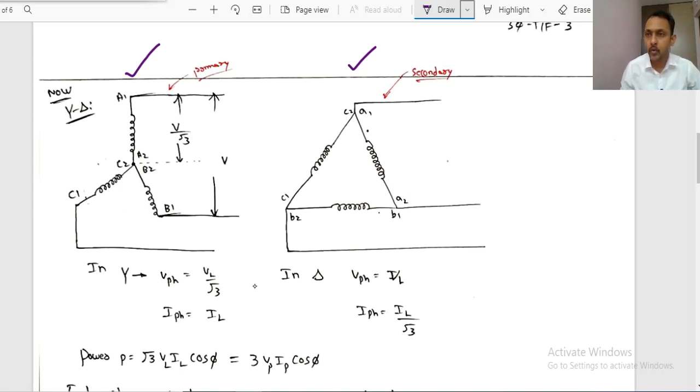Dear students, one very important point is, if somewhere you have seen some 200 by 400 volts and nothing is specified, this 200 and 400 represents the line values. Those are not the phase values or instantaneous values or some other values. Those represent the line to line RMS values. This 400 represents the V between lines, the line to line RMS value. This point is important, right?